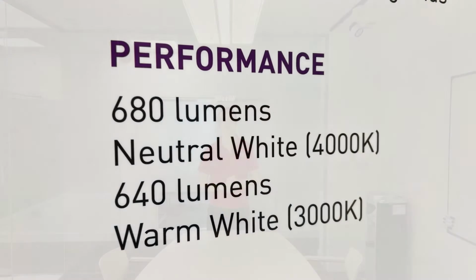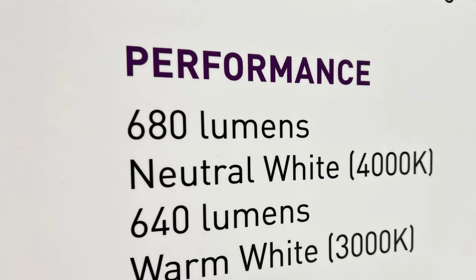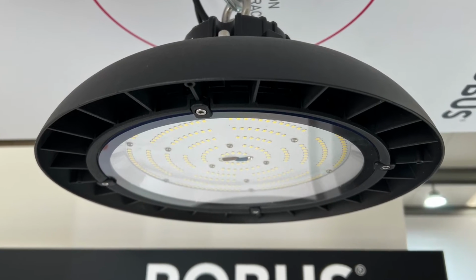Manufacturers of light fittings will tell you how many lumens they give off, and so you can divide the number of lumens required by the lumen output of your fitting, and this will tell you how many fittings you need. Now, at this point, your options really open up. You could meet the lumen requirement by installing one massively powerful fitting in the middle of the ceiling and have the right amount of lighting, or you could flood the ceiling with loads of tiny little lights with smaller outputs.